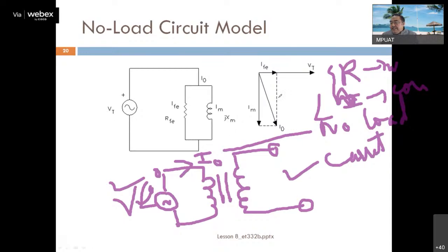Therefore, whenever a resistance and inductance are there in a circuit, what will happen? Will the current lead or lag? Lag. The current will definitely lag. This is very clear, and that is shown in the phasor diagram. Mind it, the phasor diagram is very important in our whole study of machines. If you want to understand the machine, you have to understand the phasor diagram.